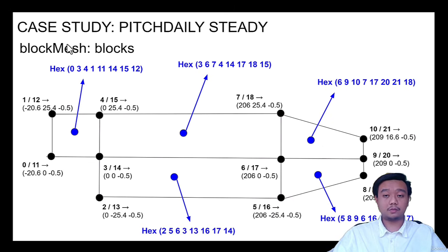If you want to modify this, for example, to increase the length of these blocks, you can just edit the x coordinates. Or if you want to delete this part to make just a straight flow, you can delete these two blocks, because some benchmark studies just use these three parts of the blocks.